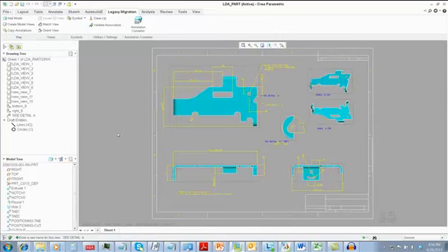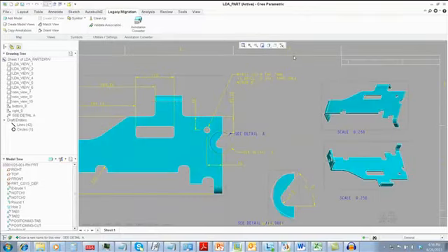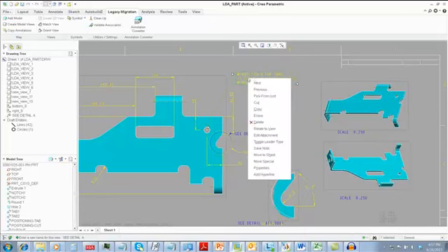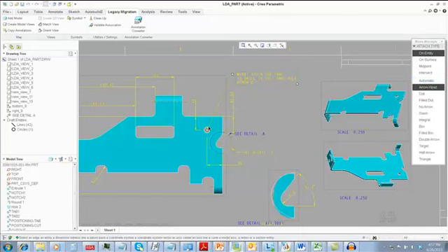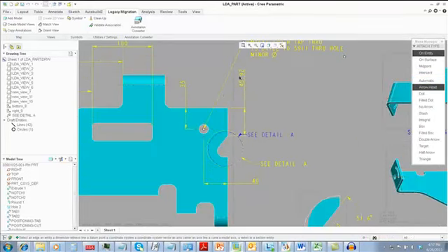There are sometimes perfectly valid 2D entities and notes that we wish to reuse from the imported drawing and relate to the solid view, such that if the solid view moves, these entities and notes will move along with it. Let's do this with this note here. The note leaders can also be attached to actual geometry using an edit attachment command, as shown here.